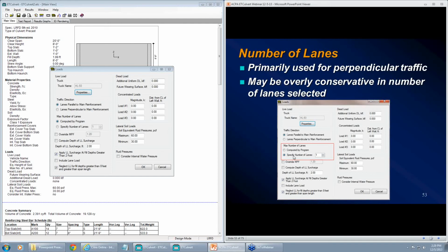All right. Now, one other question we get in conjunction with this is, why are you only using the 10-foot lane? The code says you have a 10-foot loaded section of a 12-foot lane. Well, it also says you can place that 10-foot loaded section anywhere within that 12-foot lane, and that would make our moving load algorithm way too complex. So we go a little conservative, and we just use all 10-foot lanes, and it seems to work just fine.